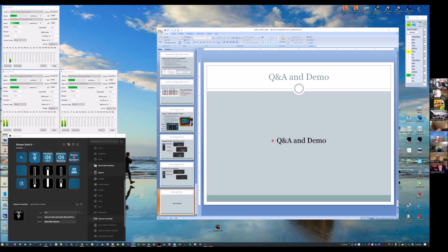Let me see how my equalization is set. Okay, so I'm set with flat equalization. You're listening through a 6 kilohertz wide filter on the left radio. That's not how I run normally, but I tried to get as broad audio as I could. So this is the CM500 with no equalization. It probably sounds a little bit compressed compared to what it was before.